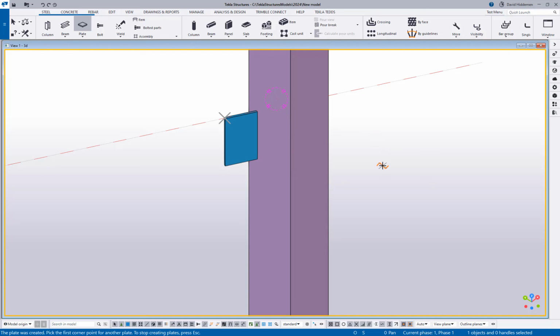Now, of course, we have components for that sort of thing, but if you ever do get into manual modeling, I think that right there is a pretty handy set of tools to model that much quicker than I would have done previously. Now, that snap to intersection does work for construction lines. It does not work for construction arcs or circles, something to keep in mind.